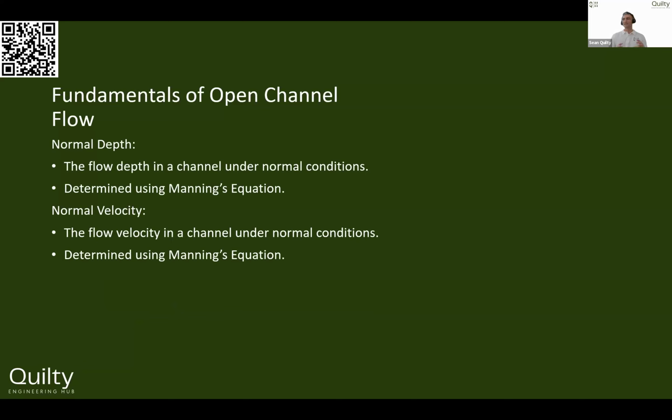So it basically means that the channel's allowed to settle, if you like, and then that flow is allowed to operate as sort of uniform flow, and there's no real disturbance, or there's nothing that's really changing those flow conditions. So it's a pretty big assumption, but if you have a reasonably uniform channel and it's a decent length and nothing's changing every 1 meter, then you could probably take those assumptions and that'll be okay.